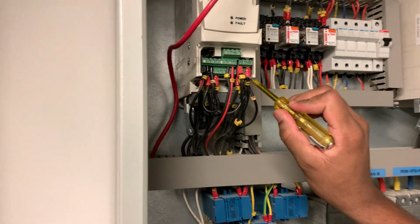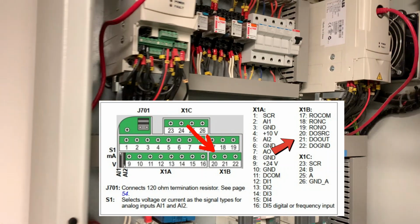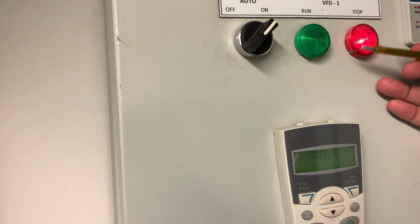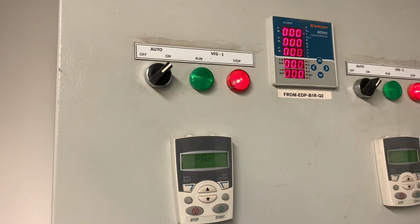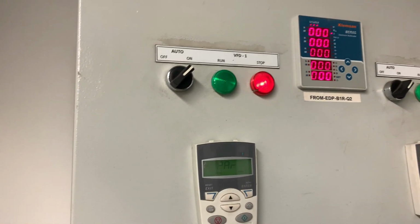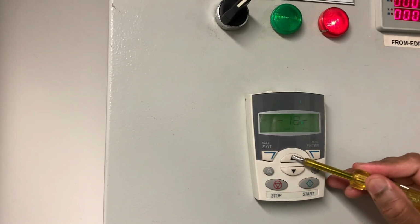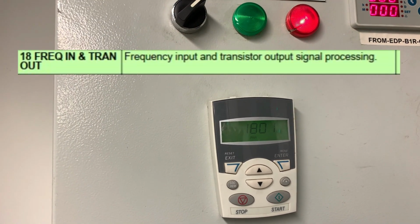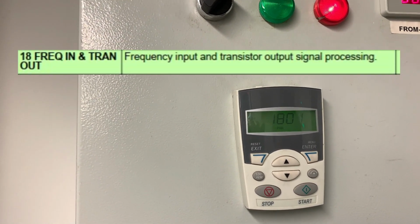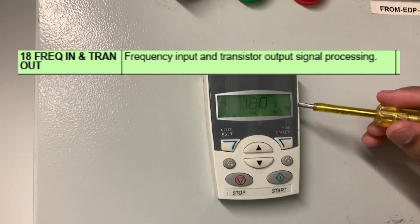Now we also have a pulse output, which I will use as a digital output pin. It means when the motor trips due to any reason, I want a feedback. I want in my BMS to know that the motor has tripped. So if you want to set that, you can use parameter 18. In parameter 18 you have to use the other digital output pin, which means the transistor output. So if you want to use that one, you have to go to parameter 18.